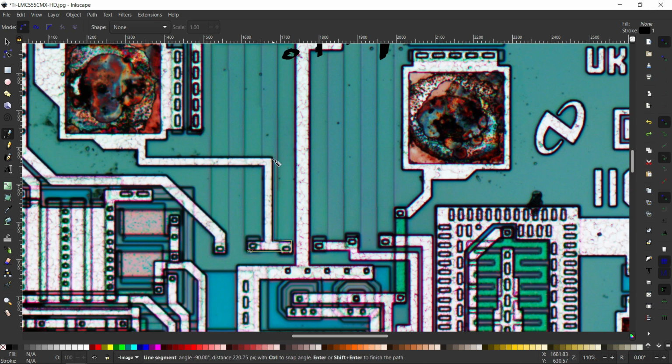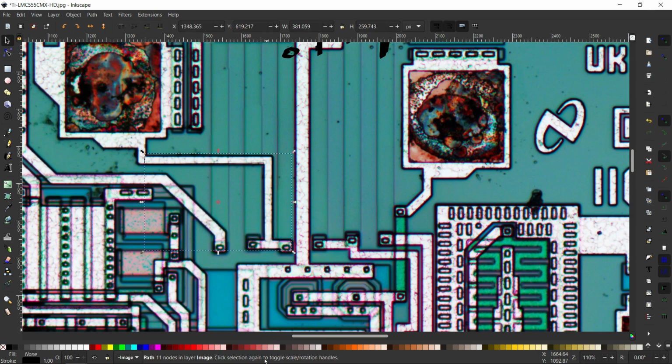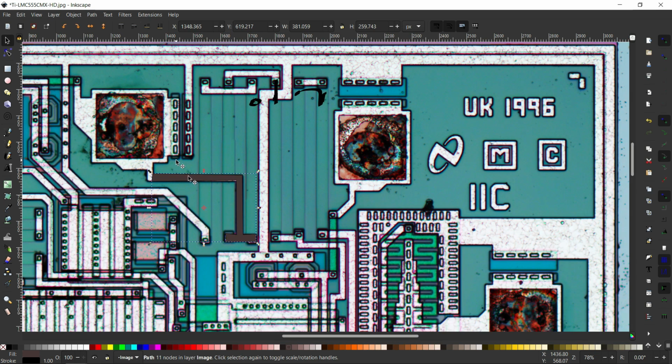See, this one is coming and connecting to a pad. Okay, so fine. I'll make it a light color. So this one, this connection from the resistor, is coming and connecting to a pad. So if you go to the schematic, whatever line is coming from the resistor and connecting to the pad, based on that we can identify what type of pad this is.